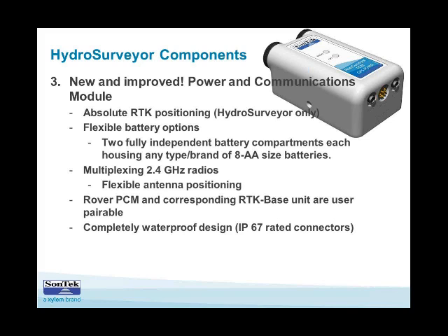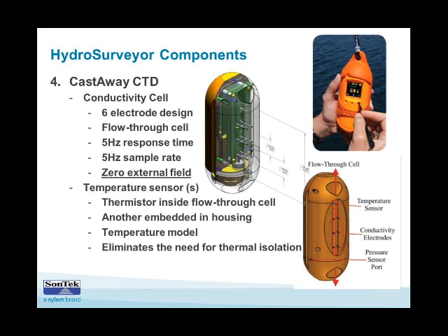And lastly, there's the optional CastAway CTD, which is fully integrated with the HydroSurveyor software and very compact. You can see in the photo in the upper right that's the real size compared to somebody's hand. Casts can be made during a survey and then brought right into the software and corrected for the acoustic information in post-processing.